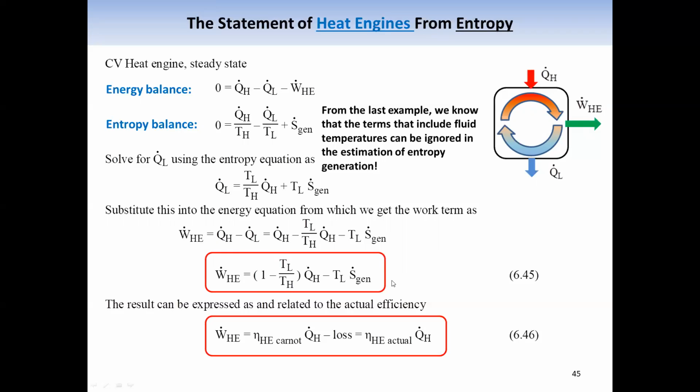If we look at the similar equation we generated for the reversible process in the last chapter, we do not have the last term. For a Carnot cycle, we have this term only. So this term is essentially the lost work, the rate of the lost work.